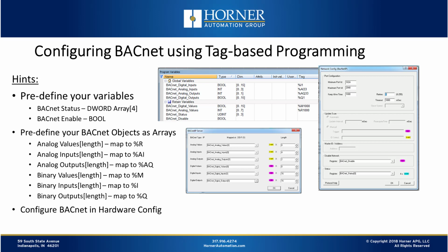Now, the screenshots I've shown you, and the demo that I'm going to be presenting shortly, use register-based addressing for BACnet configuration. That was just the choice I happened to make when I set this presentation up. There's absolutely no problem in using the more modern tag-based ladder approach for configuring BACnet and BACnet IP. So really, on this slide, we're just talking about how the process varies slightly.